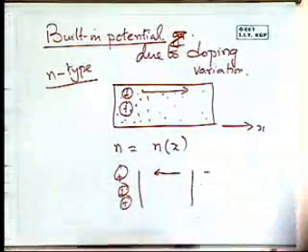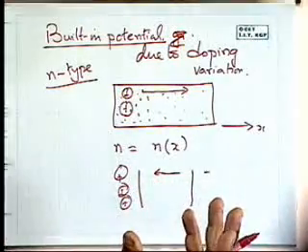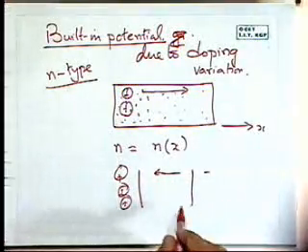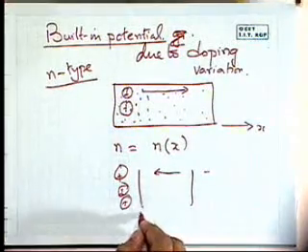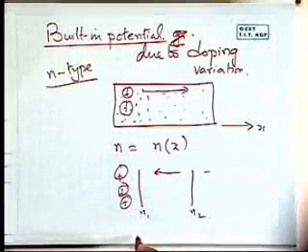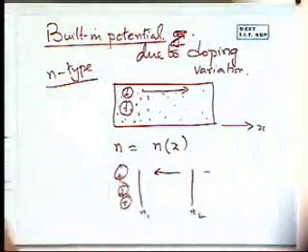And what we are interested in is to evaluate, under that equilibrium field that is established, what will be the potential difference between 2 points where the concentration is, say, N1 and N2. So now there is a potential field that has been established. It's come to equilibrium between the diffusional side of it and the drift side of it. And we want to know that at a point along X where the concentration is N1 and N2, what is the potential there, namely V1 and V2, is what we want to evaluate.